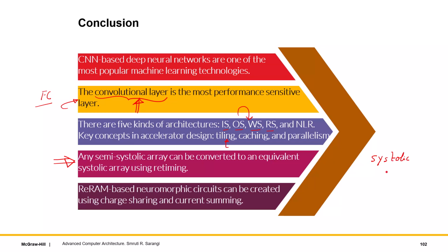Semi-systolic ones are good when you start to design because they're kind of intuitive, but they rely on broadcast connections or a tree of adders or something like that, which is not something to our liking. So we can use the retiming lemma to convert it into systolic. But a problem with the retiming lemma is that these arrays can become slow, in the sense you can slow it down by 2x or 3x, but that's fine. Multiple convolutions can be computed at the same time, so the throughput will increase.